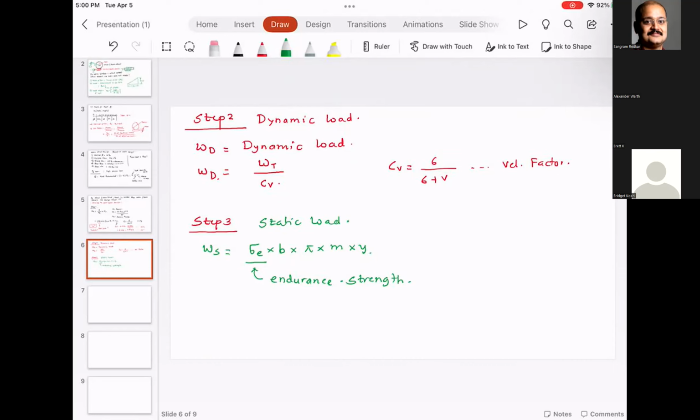After some usage, those components wear each other out to the point that the functioning is much smoother. So initially the coefficient of friction is high, after some time breaking in, the coefficient of friction stays low, and with proper lubrication, you want to maintain those two components at that low coefficient of friction.